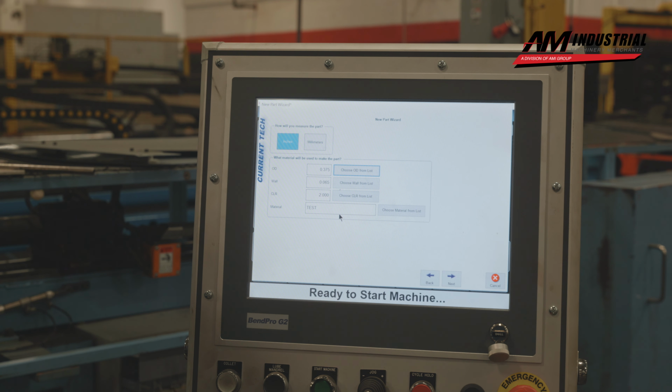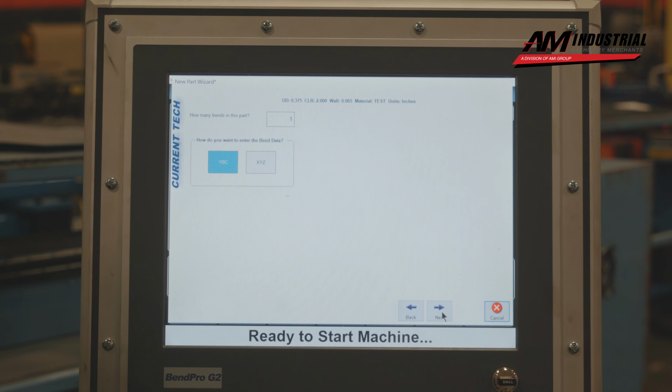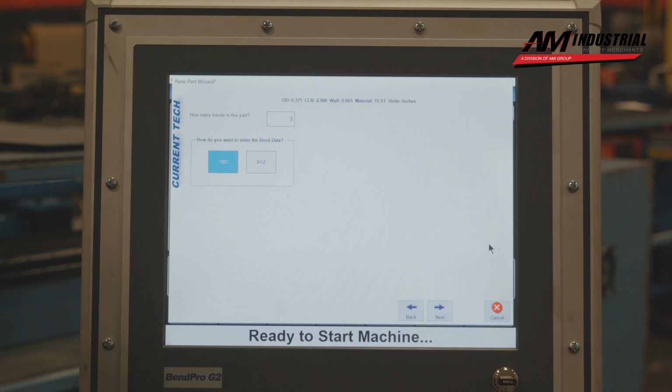And you can have different material here. You can enter in whatever you want here according to the nature of your material. In the New Part Wizard, you can always press the next button and the back button as you work your way through this. We're going to press next. We have to identify how many bends we have in our workpiece, which today it's 3. We're going to enter that.